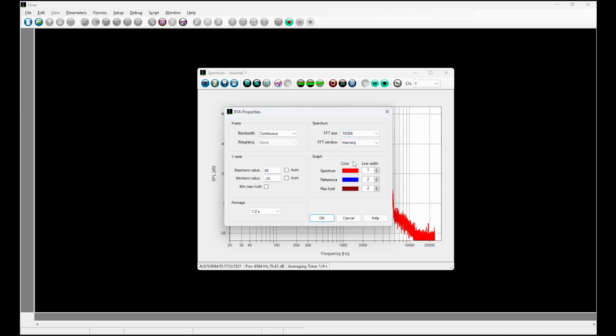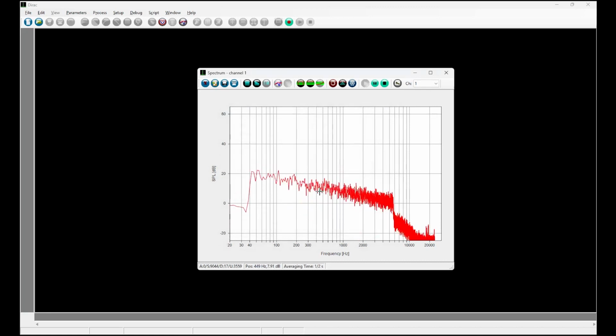And at the maximum FFT size, the frequency step size is as low as 2.9 Hz, representing a high frequency resolution, which is reflected by steep flanks, now accurately displaying the band filter magnitude transfer characteristic of the noise generator.